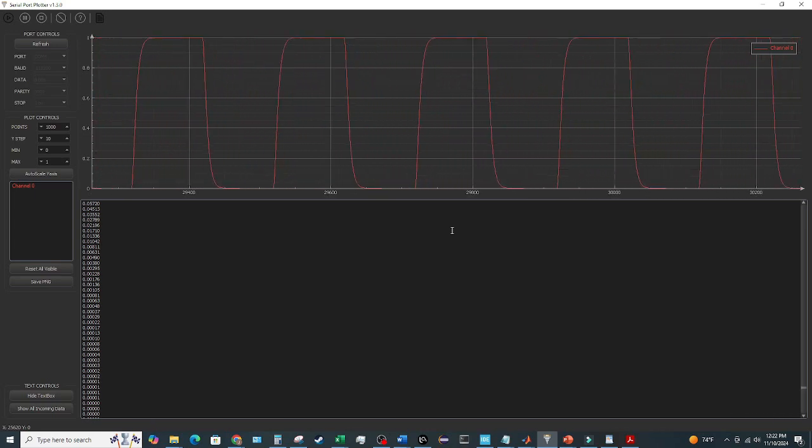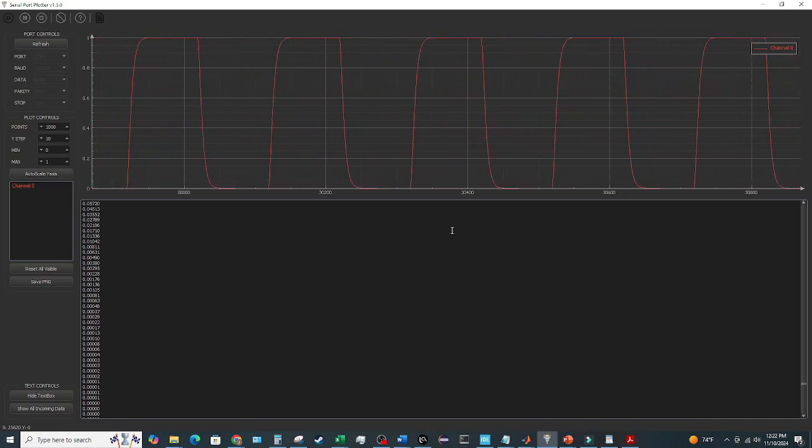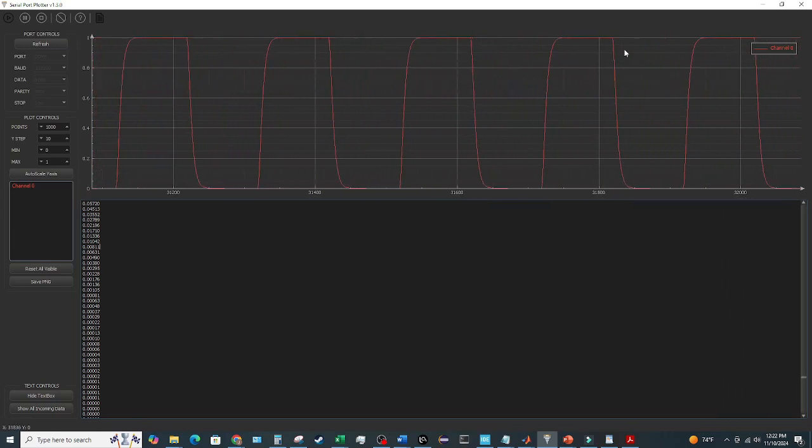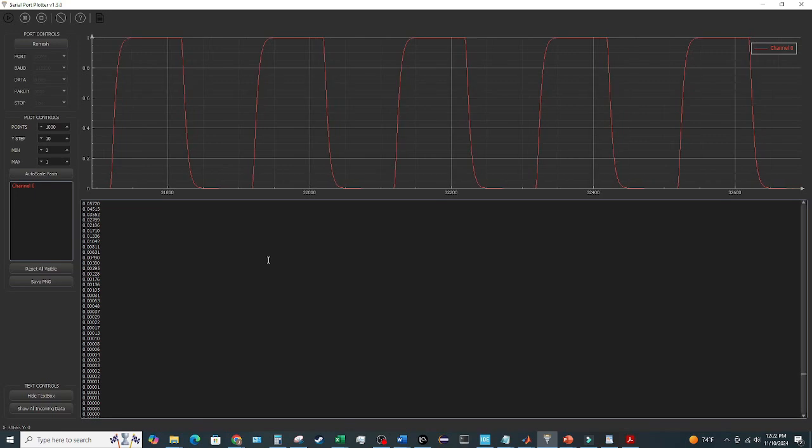Okay, so anyway, the point is, this is plotting the response of this second order system, right? So we can change those system values to whatever we want, omega sub n and zeta, and it's going to give us the step response. If we were to change that omega sub n, it wouldn't change the dampedness necessarily, but it would change the response time. But anyway, you get the idea.